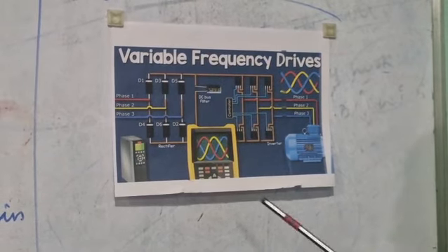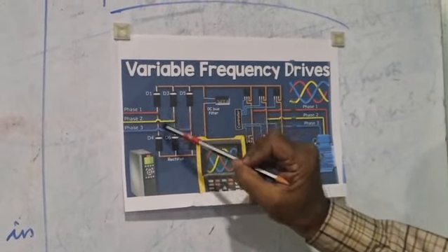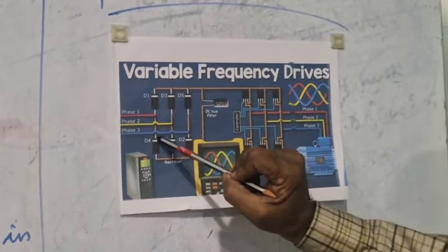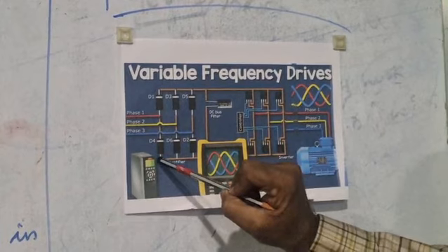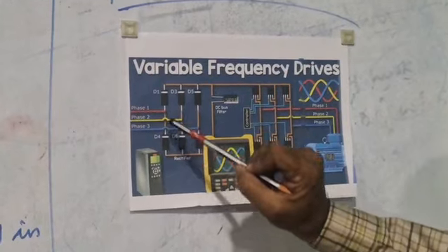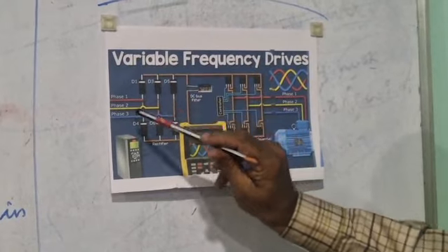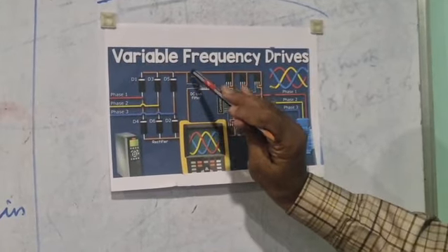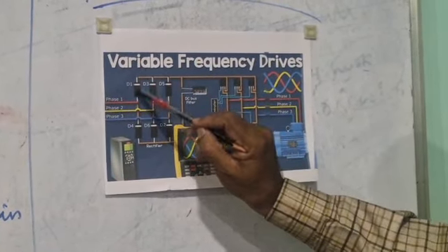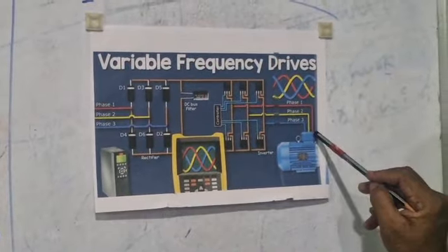VFD testing through multimeter. If you check with the multimeter, positive here, negative here, if it shows continuity in diode mode, it shows 0.3 volt, it is okay. Here, if you put the negative probe here and the positive probe here, that is reverse bias. It shows 0.36 volt in diode mode, it is okay. You need to check all the rectifier circuits; if all diodes are okay, you will get an output of 220 volts. If any rectifier circuit fails, if one diode fails, then the corresponding voltage, instead of 220, will drop down to 110 volts, and then the output won't come.